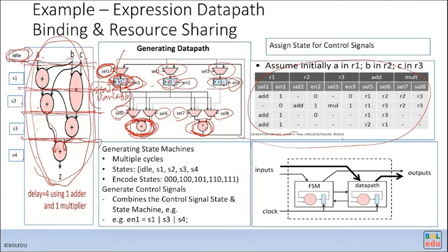You can see in this cycle you have A, B, C, so at least you want to save A, B, C. On this cycle, you have 2 passing. For this cycle, you have 1, 2, 3 edges crossing the clock cycle. And here you have 2. So you know you need a maximum of 3 state variables.